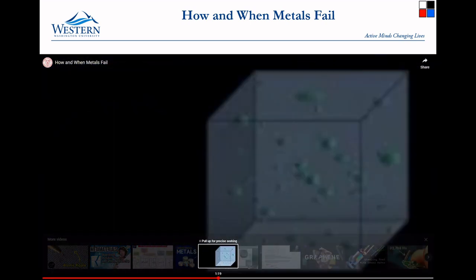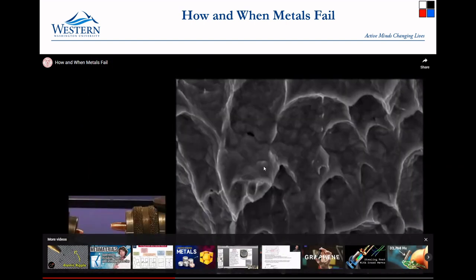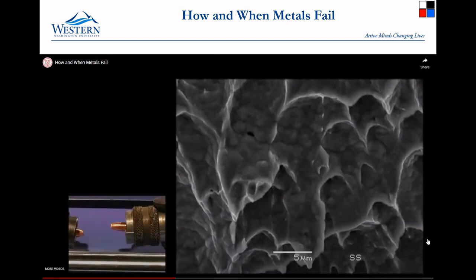When you hear them talk about doing failure analysis on something, and they say it failed in fatigue after 50,000 cycles, or they say it just failed because of overloading. The way that they know that, when they go and scrape up a plane crash or whatever, and start looking at the parts, is they look at the surfaces that broke, and they look for this ductile dimple failure.